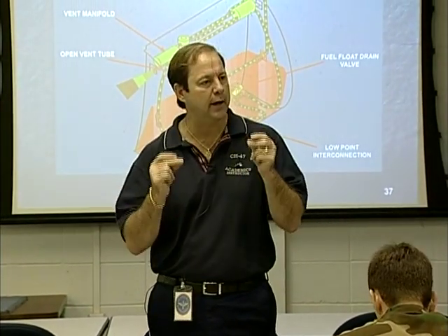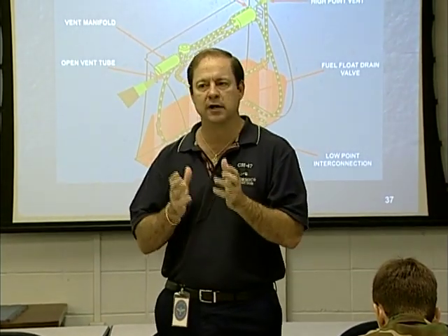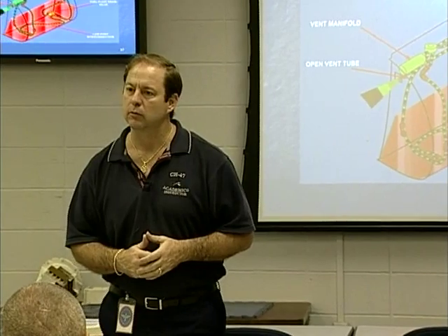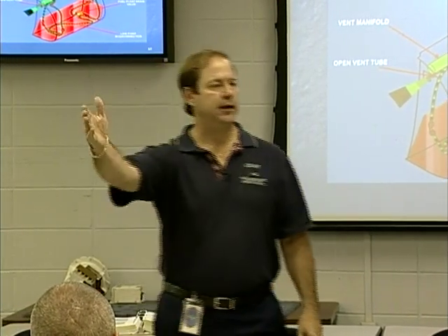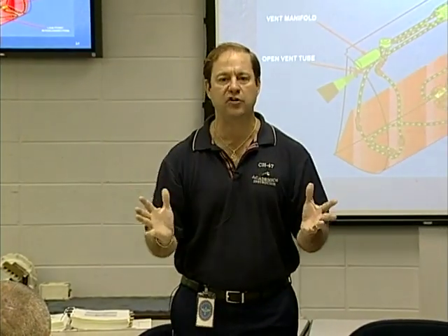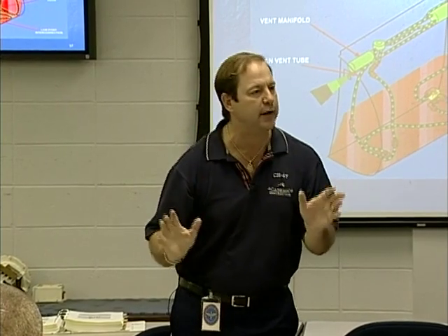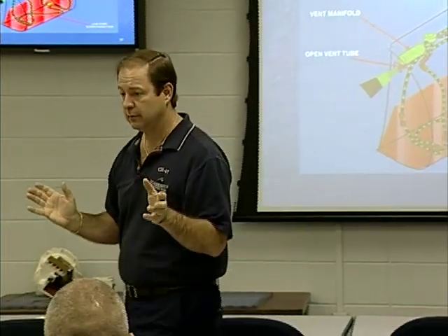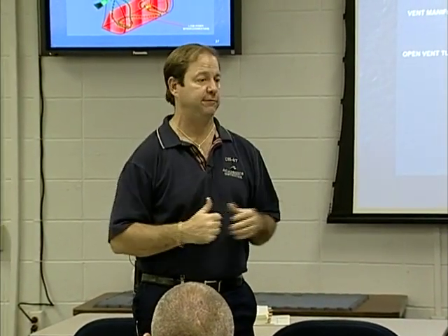And see, this is why I want you to have a good concept. Where are we going to check? Checking your fuel quantity gauge if it's more than 2,000 pounds in the main tank. Thank you. Notice he didn't say aux tanks. He went straight to the main tanks. Now, reality is, you might even want to consider just turning off the aux pumps until we figure out where it is.